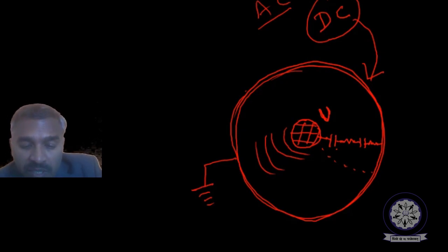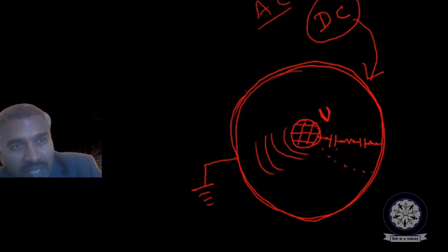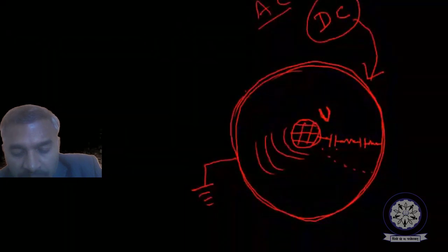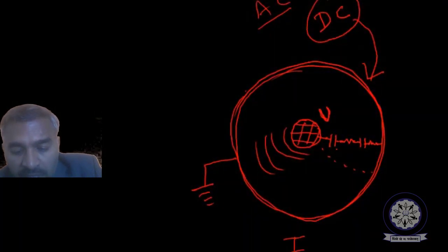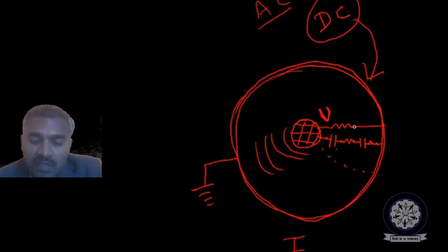Okay. So that's why in equivalent circuits, the series circuit is more suitable for the AC case, because in the AC case the loss phenomenon is also related to displacement current. But in the DC case, the loss phenomenon is related to leakage current which flows through the dielectric, across the dielectric. Therefore there must be a parallel resistance. That's what I said.